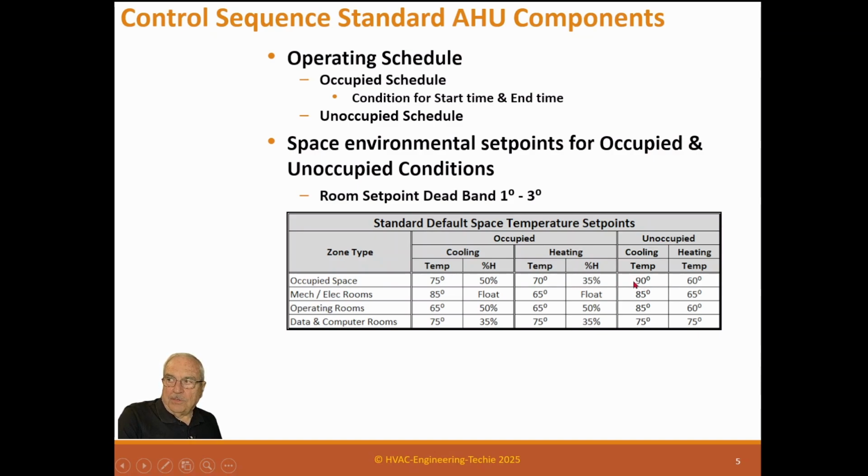The key number here: you need to take your building and calculate how much energy it takes to get the building from 90 degrees down to 75 degrees. And is that amount of energy less than to keep the building at 90 degrees all night long?